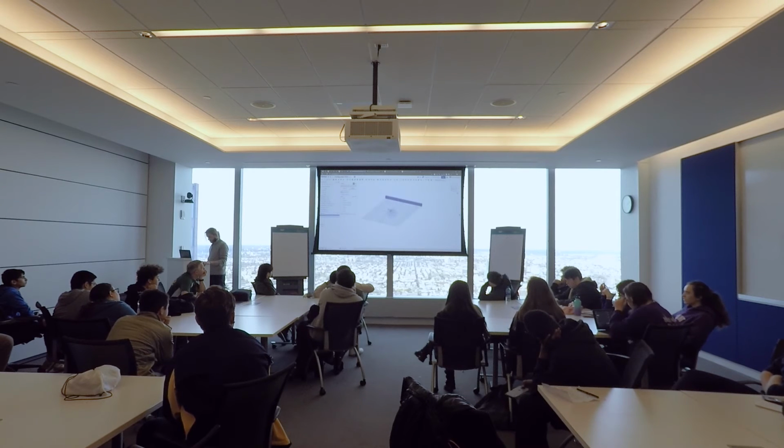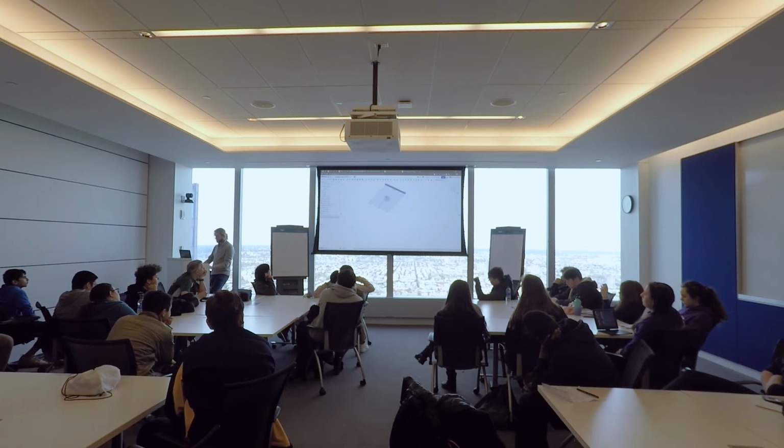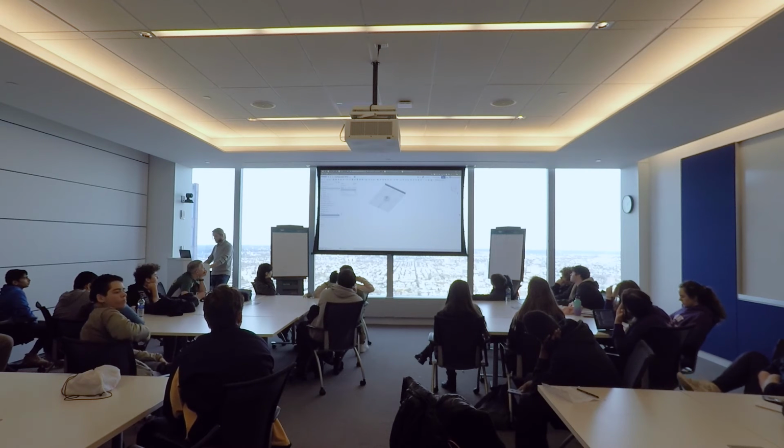Show sketch. I'm going to do this kind of thing. I'm going to trim it to this face. So see how it basically automatically shortened that for us. It didn't quite do that on this side. So maybe I should mirror it first. Okay, here's a good example of parametric modeling. I go basically back in history, and then I can do a mirror on the front plane.